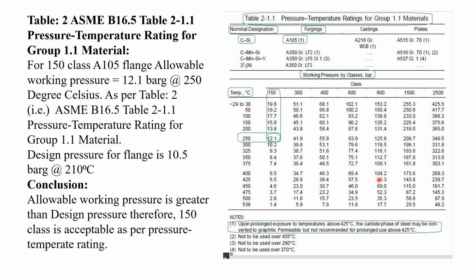Okay. So always, when there is a note put in next to material, go to notes and see what is written over here. Note 2 T4 is also the same. Okay, so our temperature is less than 210 degrees centigrade. So 425 is near to higher for our range. In that case, we can go for 150 class pressure flange.